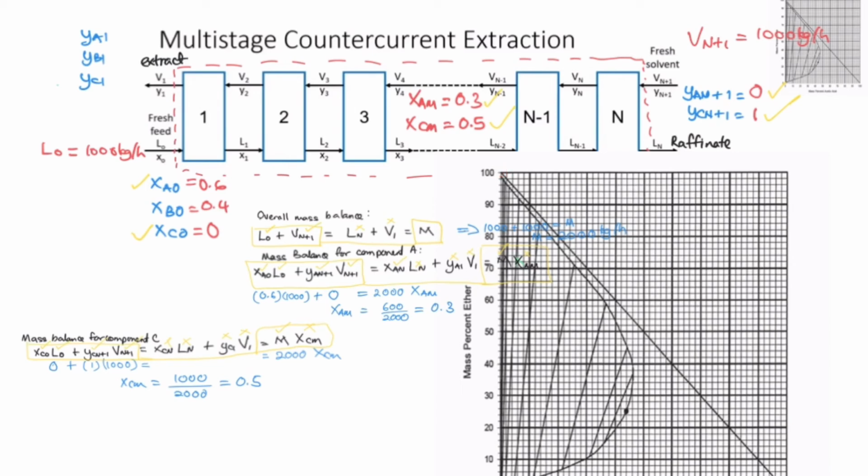So what about your V1? We don't have enough information on V1 yet. But we have some information for the raffinate. Since we assume that the raffinate composition is at equilibrium, XAN is given by a value of just now, 0.04. So you go here to XAN, you have 0.1 here, so you just take 2 boxes. You're going to draw something like this.